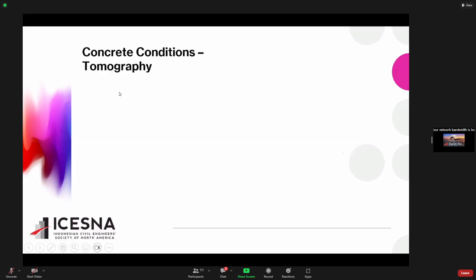Sorry, I'm going pretty fast here. It's not a new test, but it uses the CSL data, and it will create a 3D pile profile. Basically, it measures the effective area against the area with acceptable arrival time.